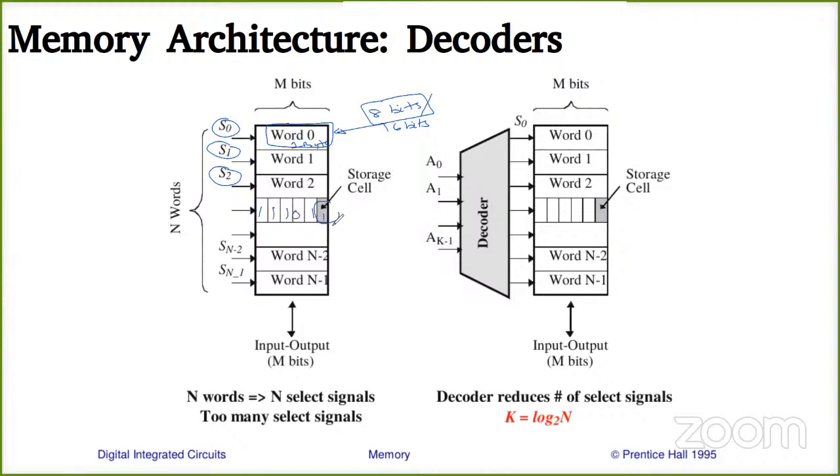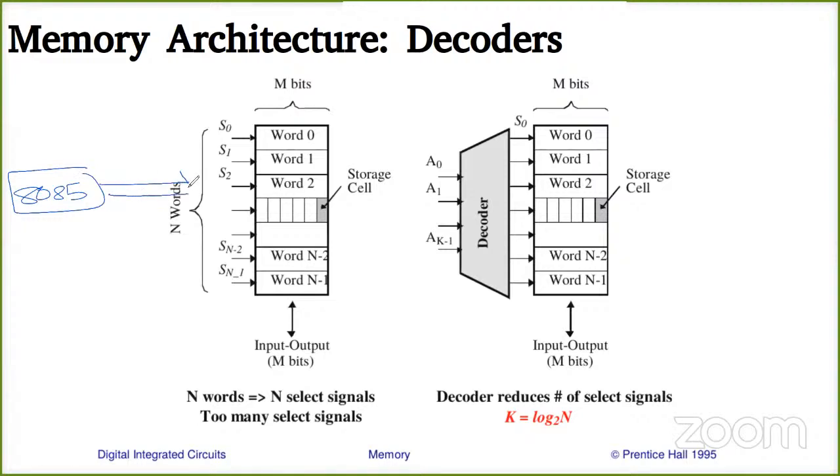So these storage elements are what? These are your individual storage elements where you will store your ones and zeros. This is what we had seen when we were talking of 8085. If you have an 8085 processor, it will talk to the memory by means of the address bus, and it will also have a data bus.